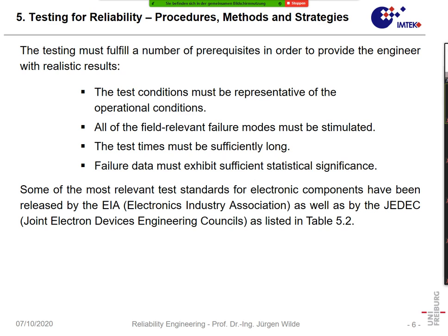That means, for instance, if the application is 3,000 hours, the test times must be such that we can be sure the product will be failure-free for these 3,000 hours. That doesn't necessarily mean we have to test for 3,000 hours.